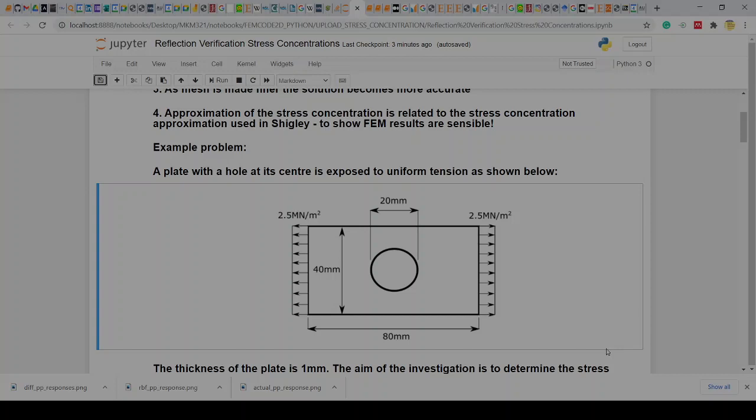A stress concentration is something different, in that there's no acute sharp angles or corners, anything involved here. This is just the fact that we have essentially a stress raiser because of some kind of a circular hole inside another plate that gets pulled open. That is essentially what we deal with in the stress concentration.